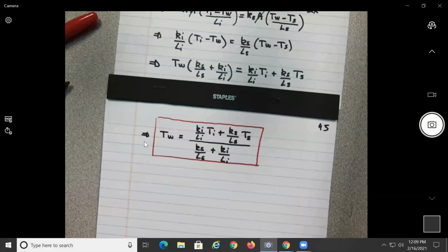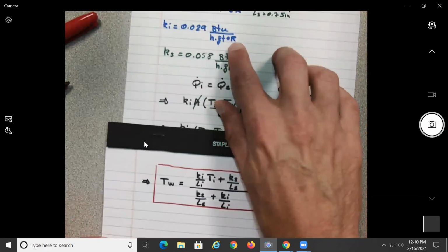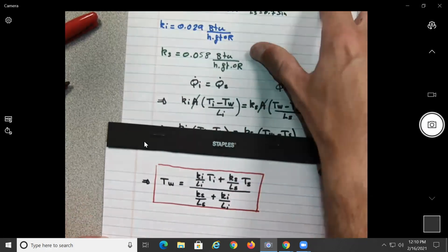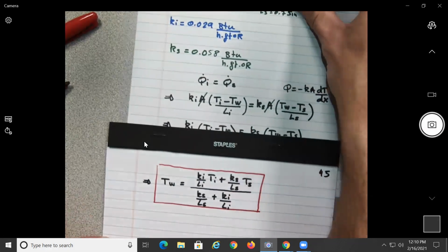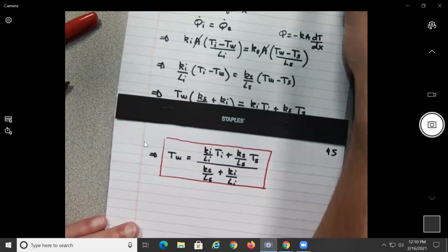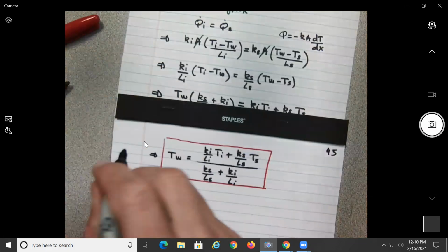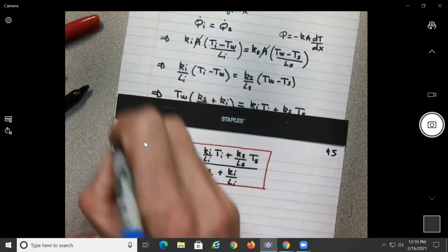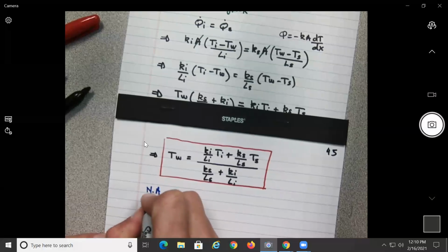So now, what is the thing where you need to be careful? Probably it's what units you're going to take the temperatures in, no? If you look at the units, the Ks are in Rankines, no? So you need to move these temperatures into Rankines. So maybe that's what the problem is, if you have any problem. So if you do the numerical application, give me the correct value.